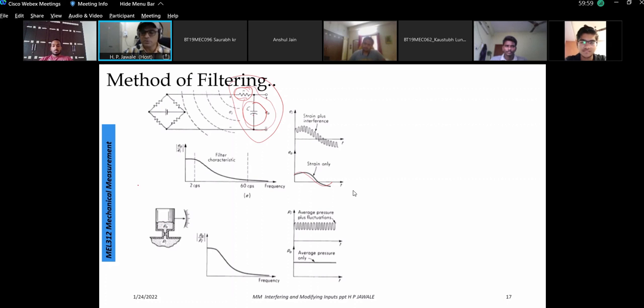Say, for example, yours is an air compressor. Because of a reciprocating compressor, the air filled in the tank is going to have some kind of fluctuation in the pressure. So instead of using a device, we are going to use an orifice. Without the orifice, the pressure sensed will fluctuate, because of the constant input of air volume from the cylinder of your reciprocating air compressor.